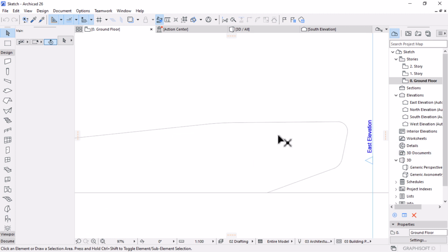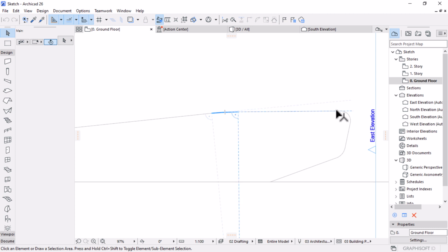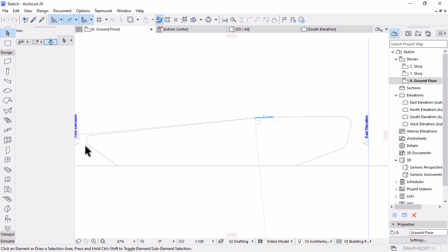This will allow you to demarcate. For example, this area will be done separately, and then you have this as a profile, or maybe this as a roof, and then this as a profile, this is an angled wall, and then this also as an angled wall. So on the curves, on the corners or curved corners, you can use a profile to achieve that, and then the remaining part of the roof is going to be a roof tool. This will be a wall or a slanted wall. Same applies to these two sides. And then you can also use a morph tool. A morph tool is easy to use and it's quicker to produce results.